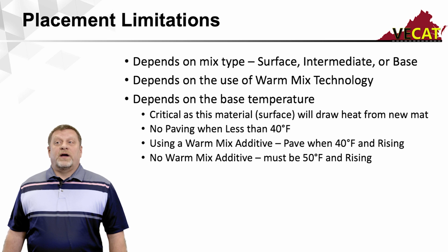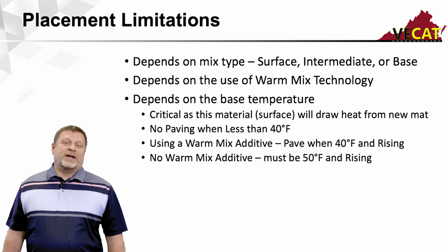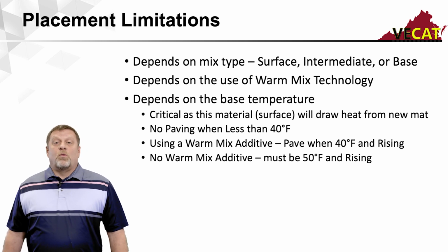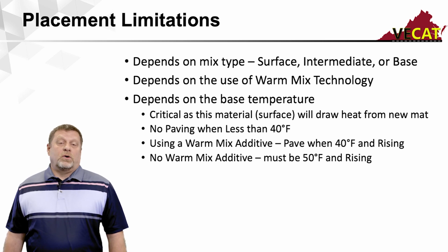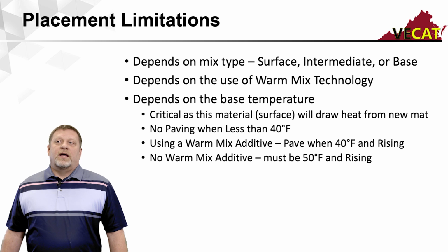Another variable we have to consider is whether or not we're using a warm mix technology. When I say technology, it can be a warm mix additive or it can be foaming. The introduction of water to foam is also considered a warm mix technology. So either one falls in what we consider a warm mix product, which affects what our placement limitations are.